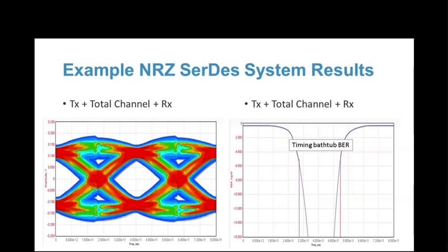The raw Monte Carlo BER curve is in red, and it goes down to, in this case, 10 to the minus 5, and the extrapolated BER goes down to 10 to the minus 16, and displaying both of them together shows that the extrapolated BER overlaps the raw data very well with a reasonable extrapolation.